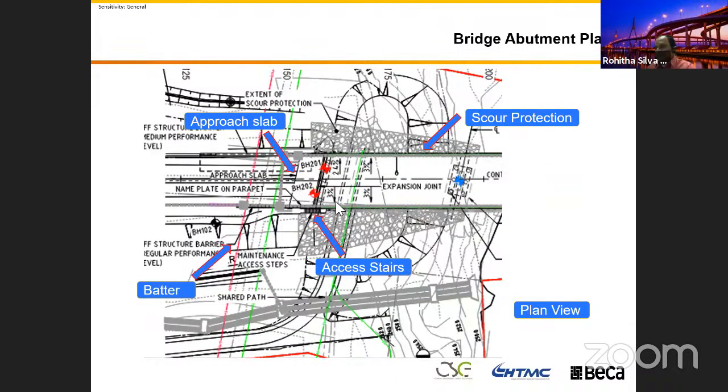Then you can't simply assemble them together, because the bridge is very rigid and the ground is really flexible. I can give you one example, my experience in Bangkok. The bridge we designed, the settlement in the bridge is on the order of about 20 mm. But in the soil over there, when you build, settlement is about 200 mm.